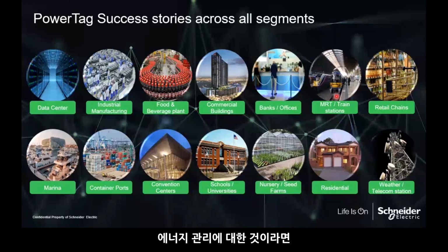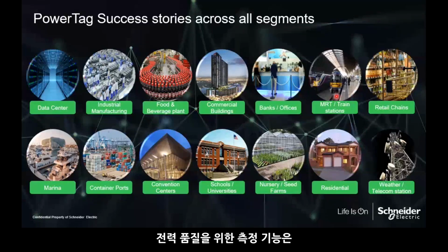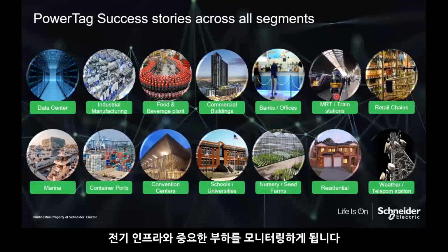Is this purely for energy efficiency and energy management? PowerTag could be a good solution, and you can go all the way down to load monitoring. But if you're in certain critical buildings or segments where power quality is required, then PowerTag is just monitoring the non-critical loads, and standalone metering with power quality functionality will monitor all the electrical infrastructure and critical loads.